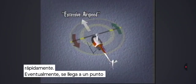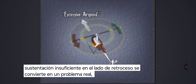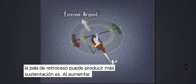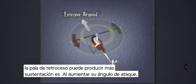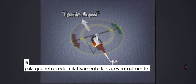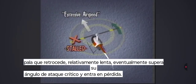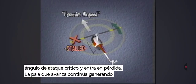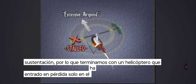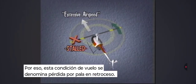As you increase your forward air speed, dissymmetry of lift grows greater and greater very quickly. You eventually reach a point where insufficient lift on the retreating side becomes a real problem, and the only way the retreating blade can produce more lift is to increase its angle of attack. Eventually, the relatively slow retreating blade exceeds its critical angle of attack and stalls. The advancing blade continues to produce lift, so we end up with a helicopter that's stalled only on the retreating side. That's why this flight condition is called retreating blade stall.